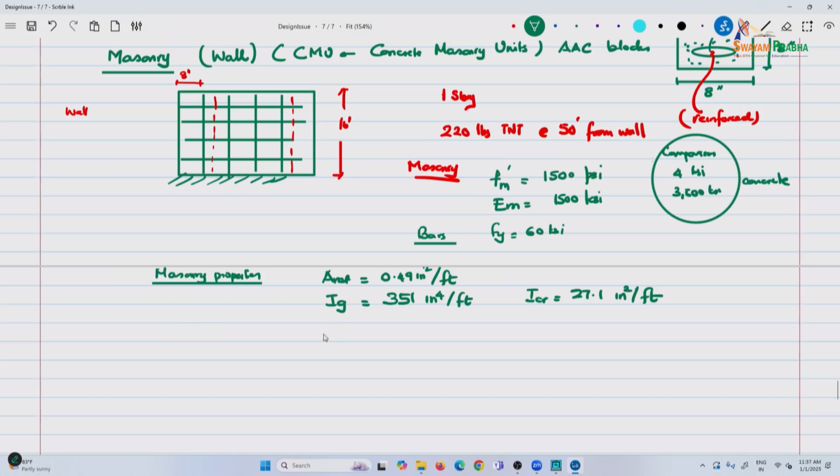and the self weight of masonry is 16, the roof, this is for the roof. So there is a roof here. So, this is 69 pounds per square foot for the roof, plus masonry itself is 40 pounds per square foot, plus any additionals you could have.